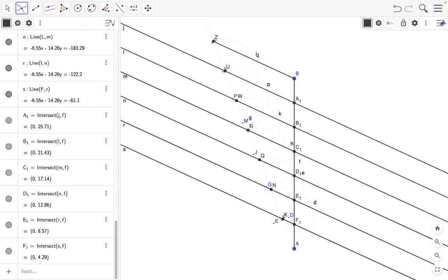Okay. So we can see that this line AB now is divided into an equal number of divisions. Here we have considered 7 divisions. So that will be useful for the construction of the letters. So here you see that A, this one 1, 2, 3, 4, 5, 6 and 7 divisions we have successfully got. This vertical line can have any orientation, arbitrary orientation, and accordingly you can draw the arbitrary line having some acute angle with that, and then follow the method of construction.